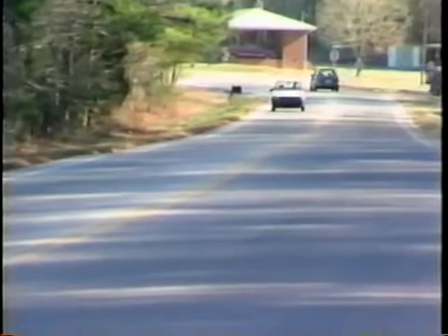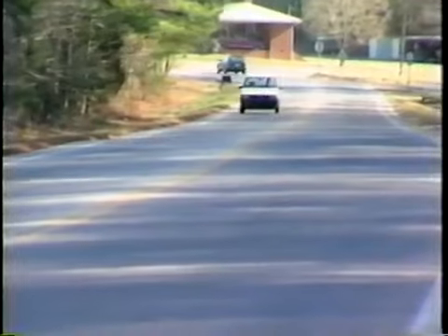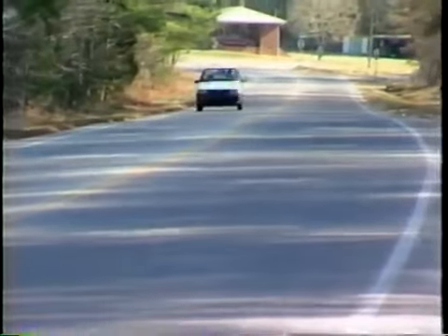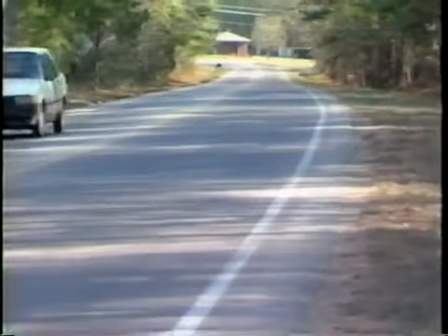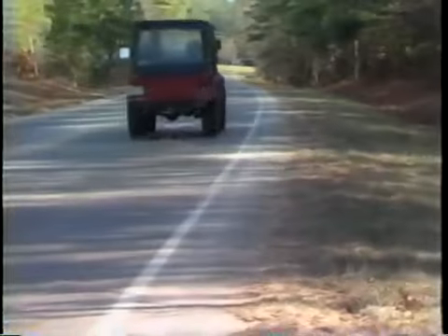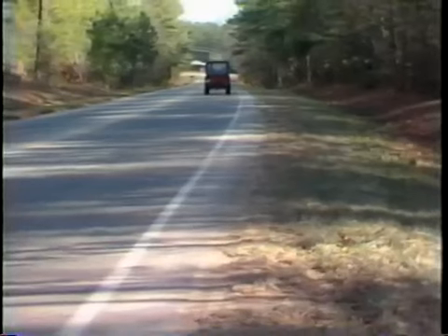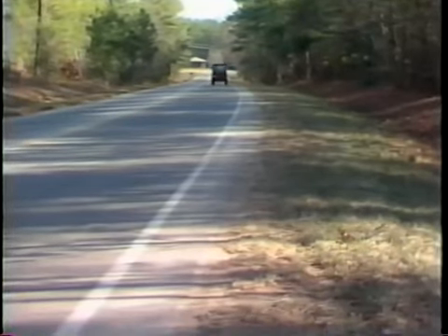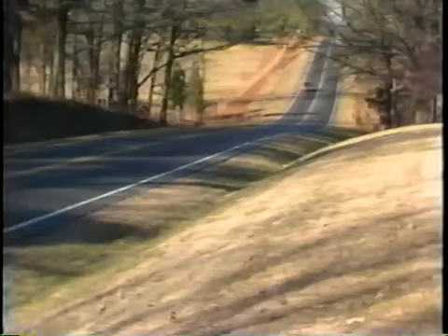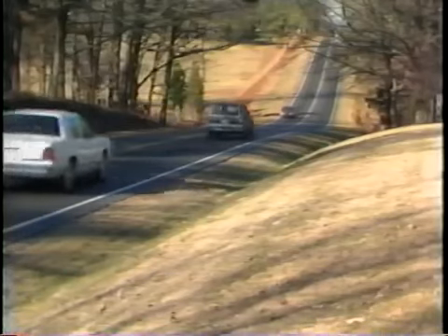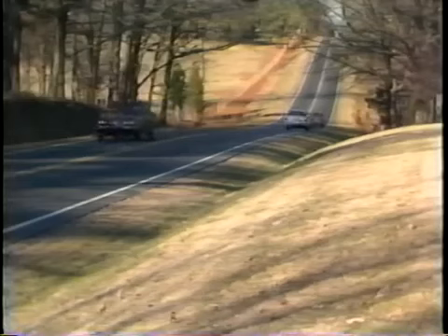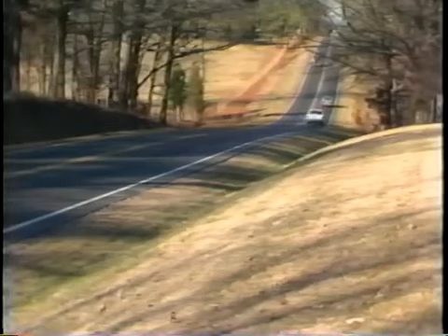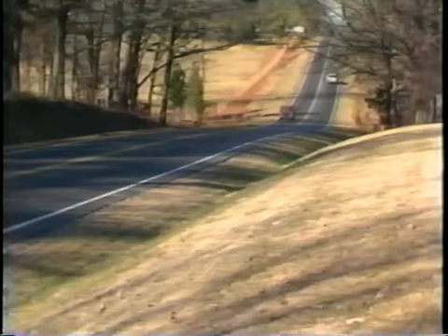Certainly, proper shoulder maintenance is important to the performance of a roadway. This roadway has properly maintained shoulders, allowing for lateral support of the pavement edge and proper drainage of surface water into the adjacent ditches. These shoulders are able to perform their intended function on the roadway. Shoulder maintenance is a necessary maintenance operation, and when done, the proper techniques should be used.